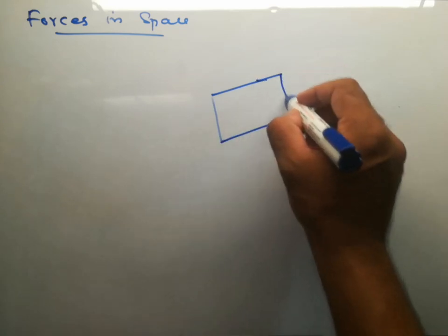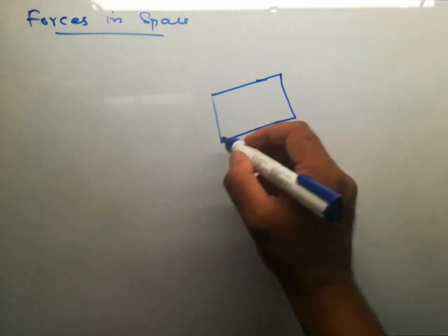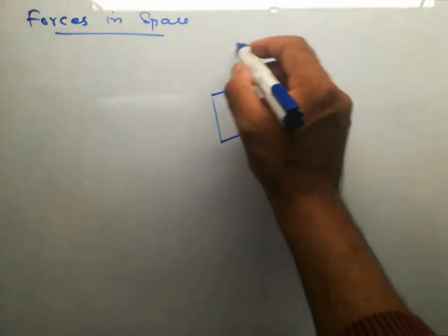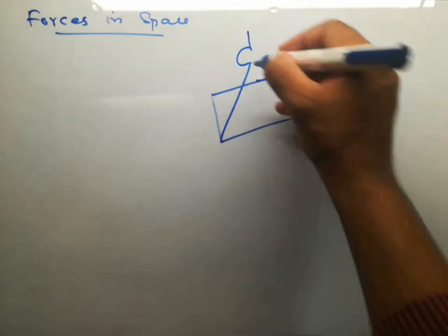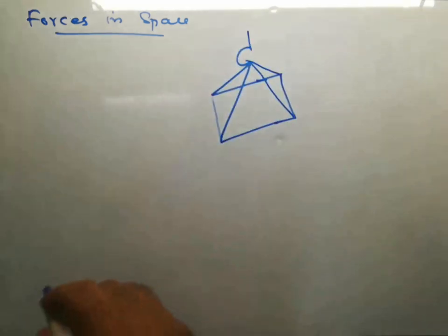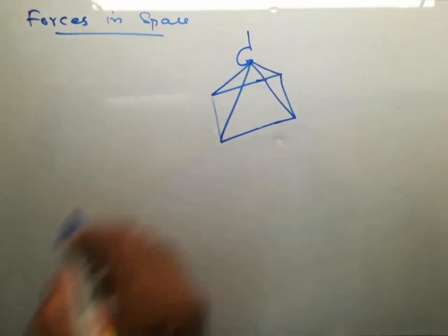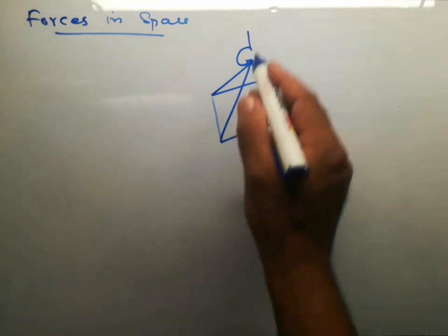and place it at the required position, what we will do, we will be using cranes like this, and attaching cables from some determined points, so that the slab will not break and it will be effectively lifted up. Like this, it will be tied to the hook of the crane, and it will be lifted up.